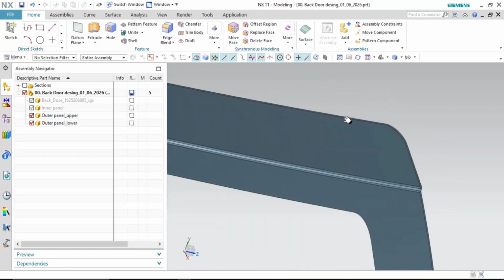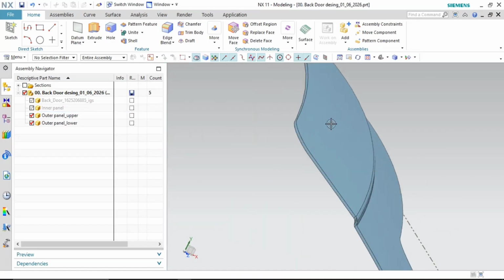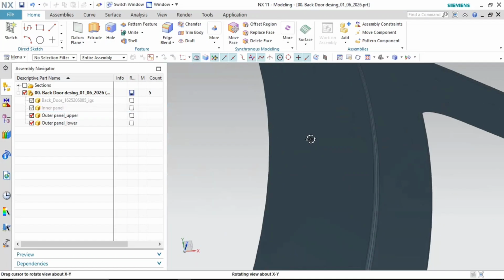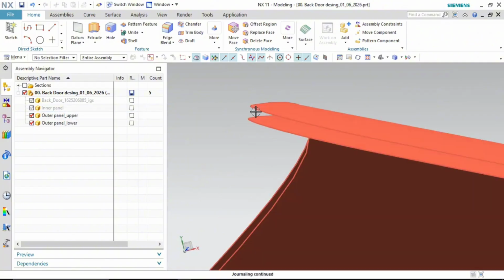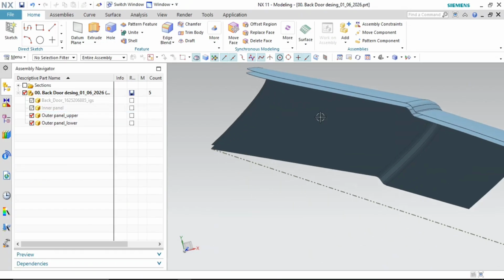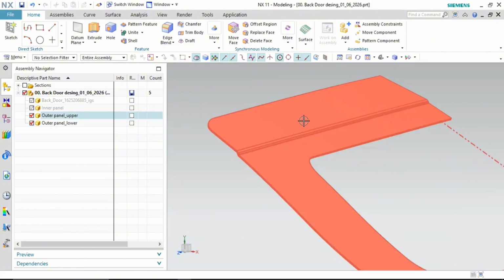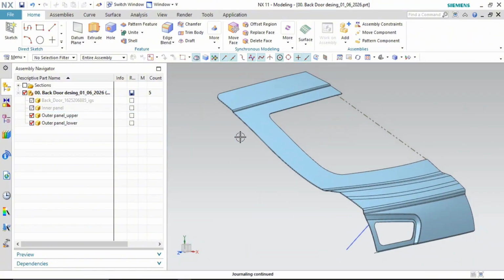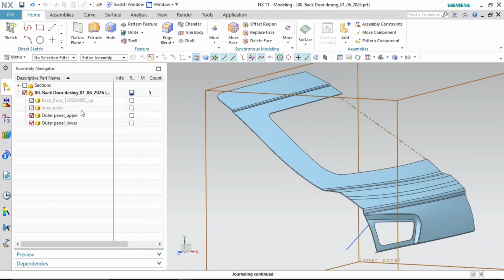This time, last time we tried a law extension option. So we created one law extension, that means one surface from this face. We tried to trim them off, and we also tried a tritangent fillet. None of the ways worked out. So in this video we are using a completely different approach.